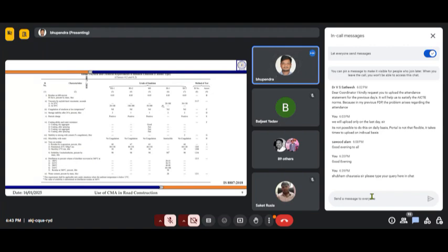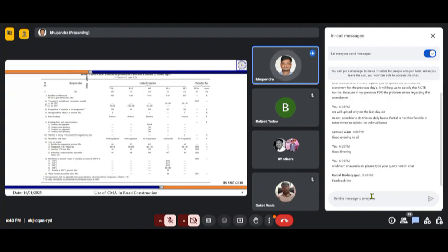And then for slow setting 1 and slow setting 2, the viscosity is checked at 25 degrees Celsius, because their viscosity is lower as compared to these. Okay, so there also values are given. So we check the viscosity, and based upon that we decide.